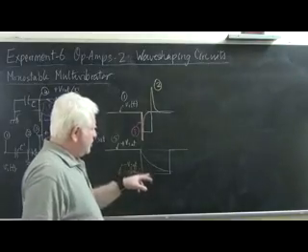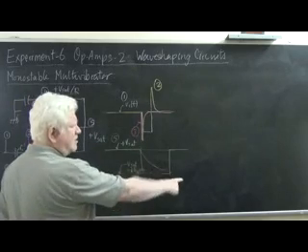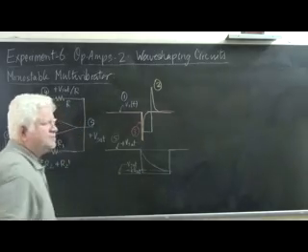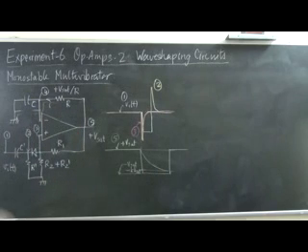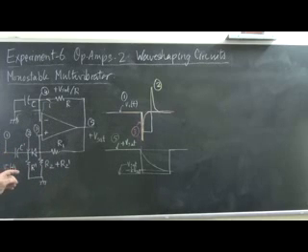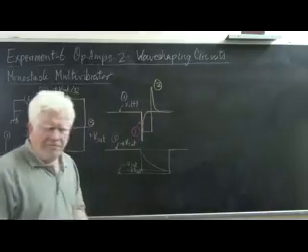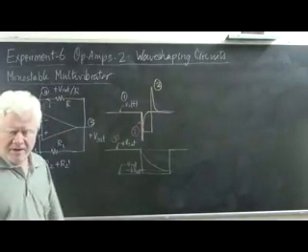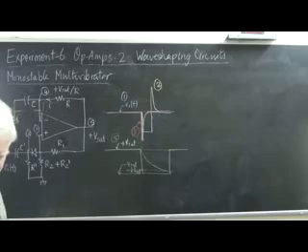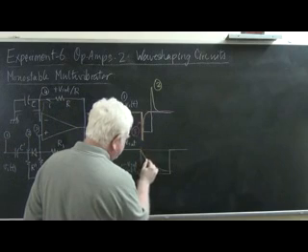The complete waveform is drawn over here. As we said, the capacitor starts charging towards minus Vsat and crosses this level of minus k Vsat at a certain point of time until the inverting terminal voltage goes below minus k Vsat. The output remains at minus Vsat, and this green waveform is the minus Vsat waveform number 5. I actually should have used a different color for the capacitor signal, so let me use yellow over here, and this is the capacitor charging curve.